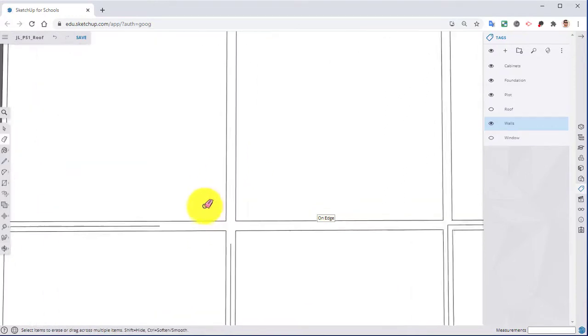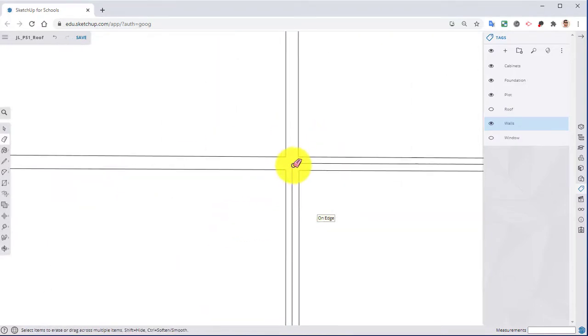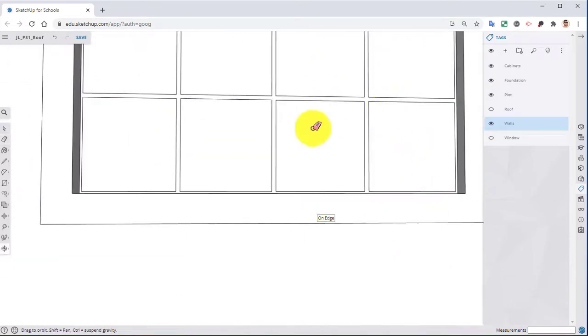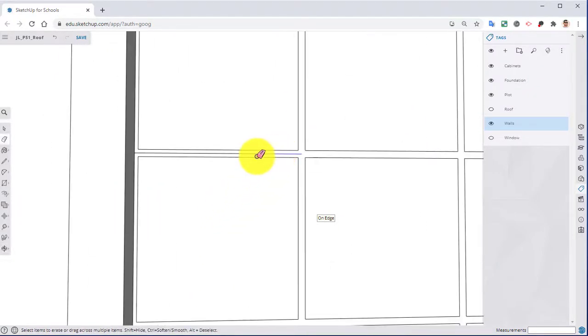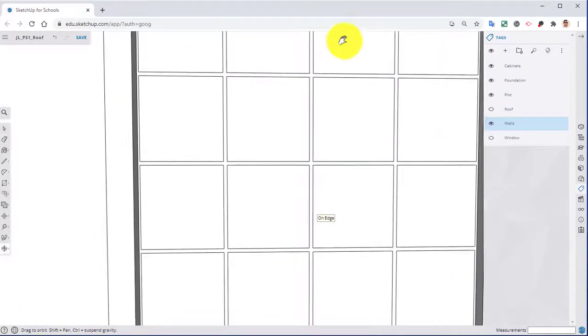And we're going to go in here and use the push-pull tool and pull this face back one way, and then make a copy of it and put it the other way. Remember, if you mess up anywhere, just hit Control Z, undo it. Make sure we go through, and there are no spare lines going anywhere.